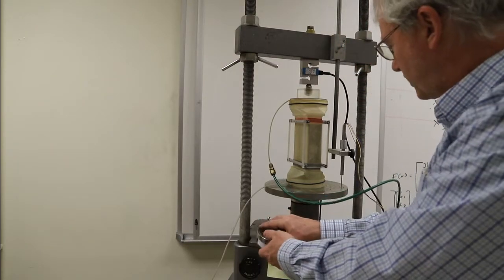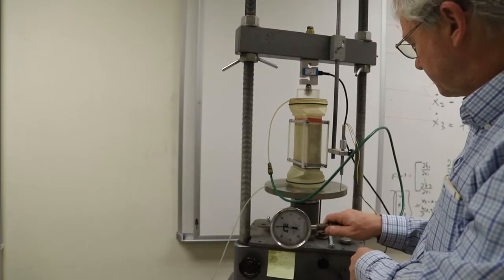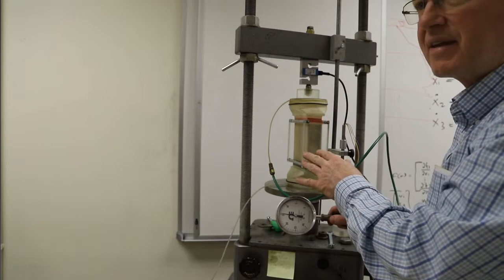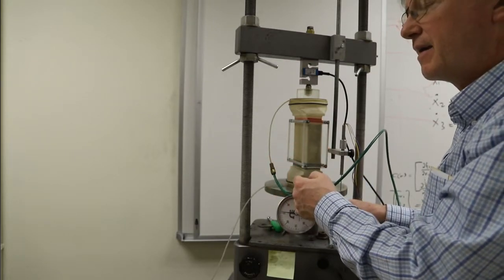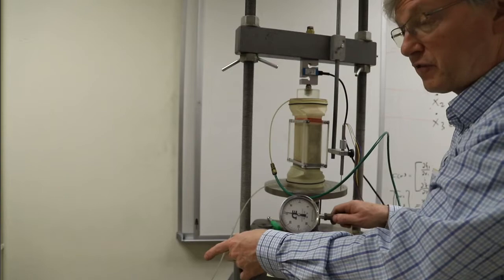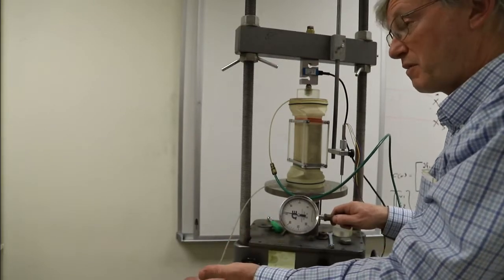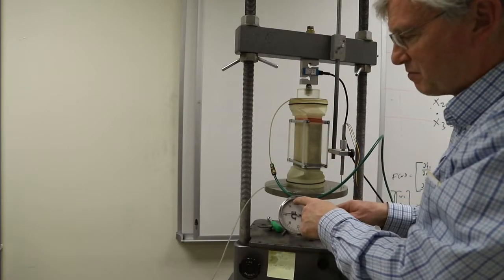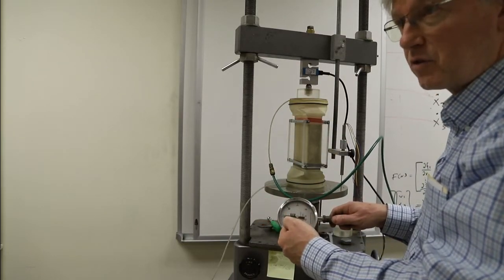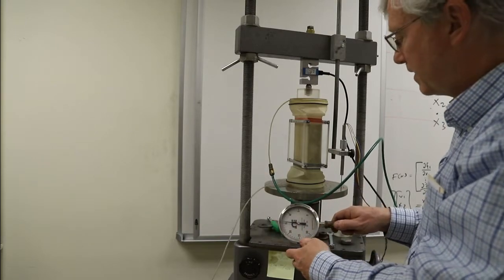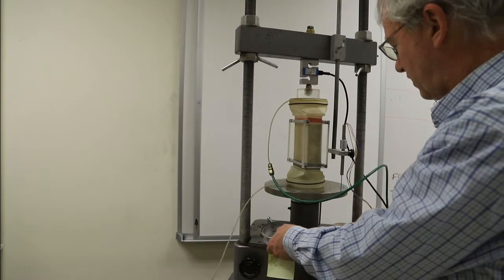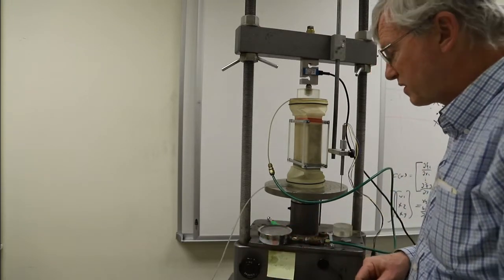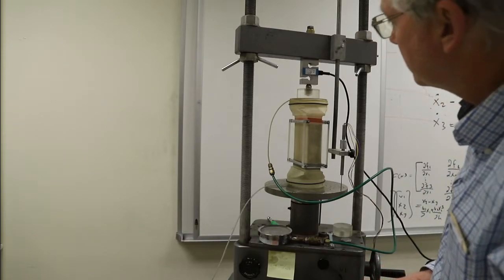Oh, and I didn't mention, why do I have a second gauge? It's attached to the top. So if I had a slow leak in the system or a minor leak, I might think I was applying 50 kPa of vacuum to the bottom, but up at the top I might only be measuring 37 or 42 or something like that, and that would be a good indication that somewhere at a corner or somewhere, maybe at an O-ring seal, there was a leak. But I'm seeing good agreement between these two, so I think we're in good shape.